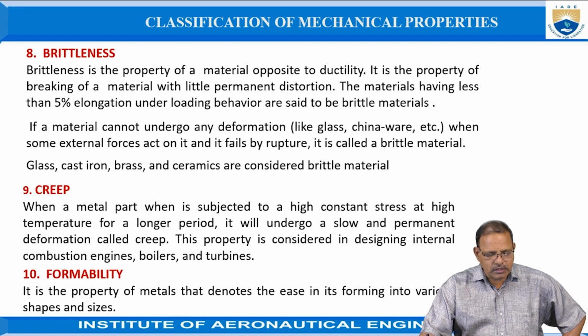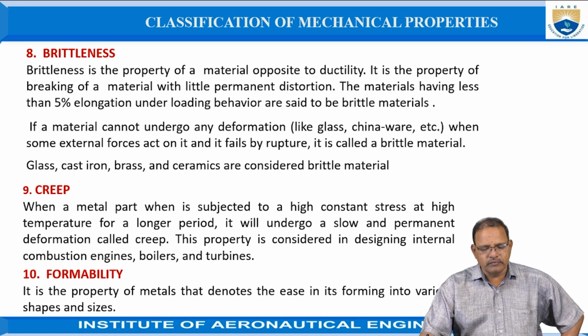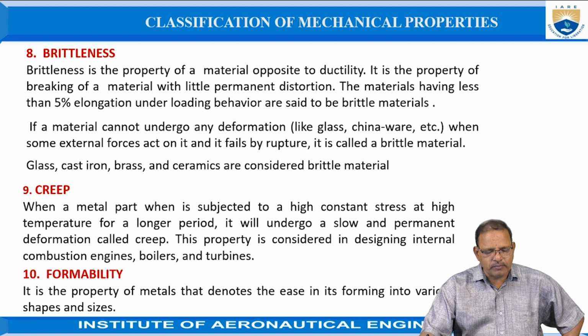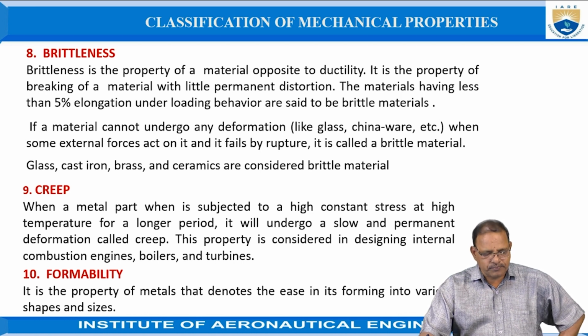Creep. When a metal part is subjected to high constant stress at high temperature for a longer period, it will undergo slow deformation. Slow and permanent deformation is called creep. These properties are considered in designing such things as internal combustion engines, boilers, and turbines.